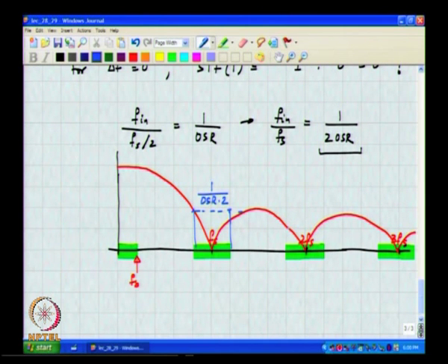What about the attenuation here in the second alias band? It will be at least delta f by 2 plus delta f, which is very small compared to 2. So, it is roughly 1 by 4 OSR. And 1 by 6 OSR and so on. Okay. All right.